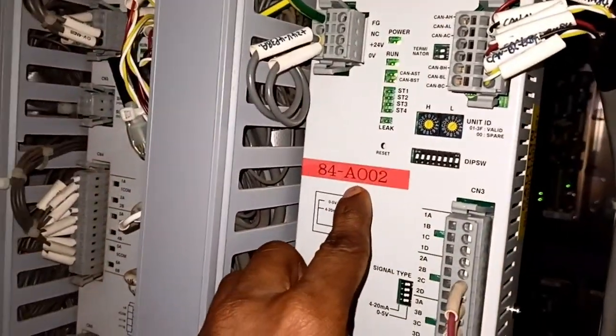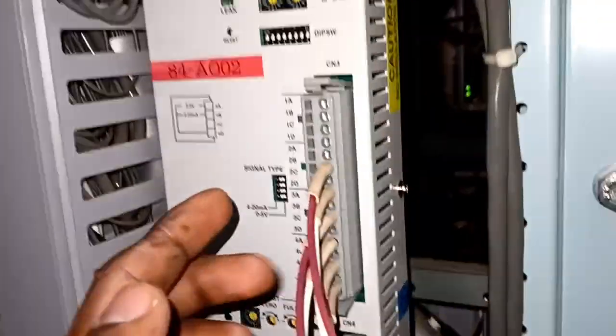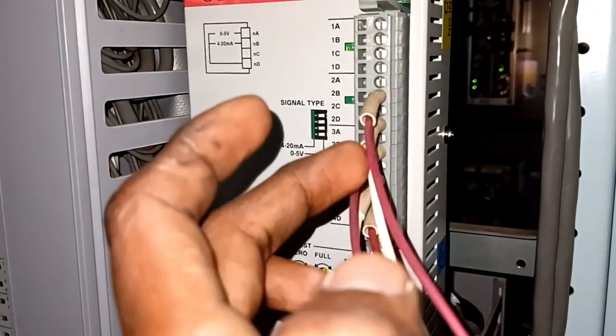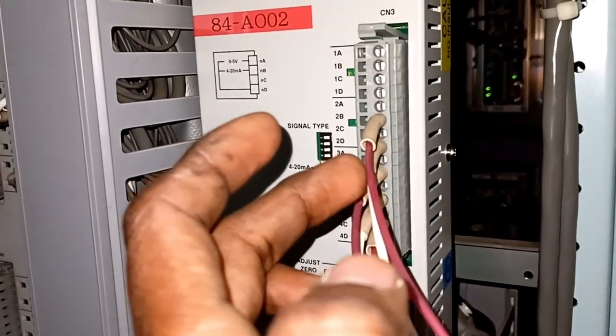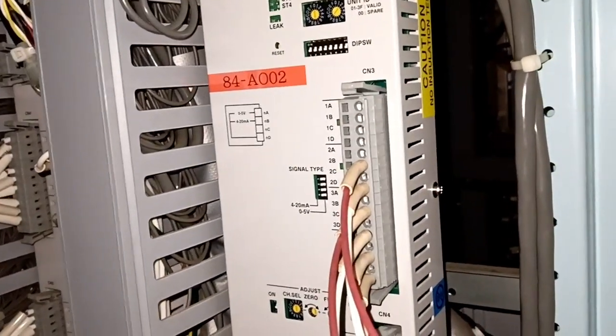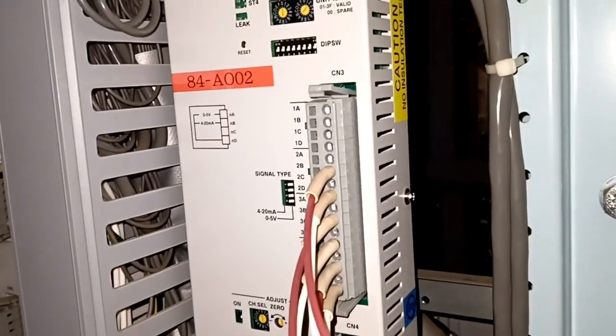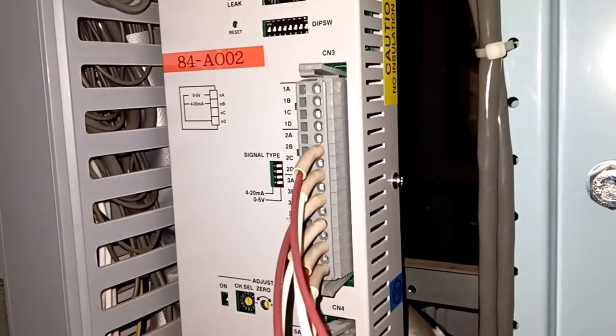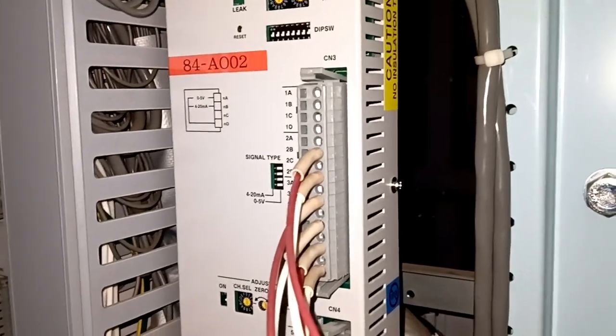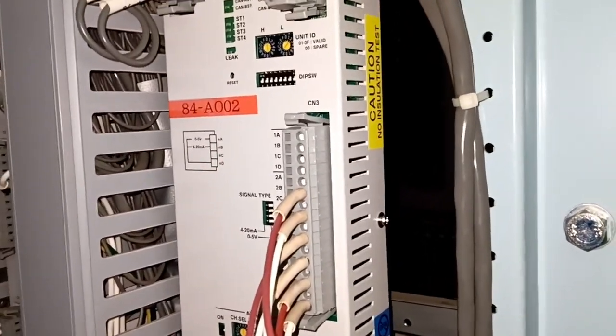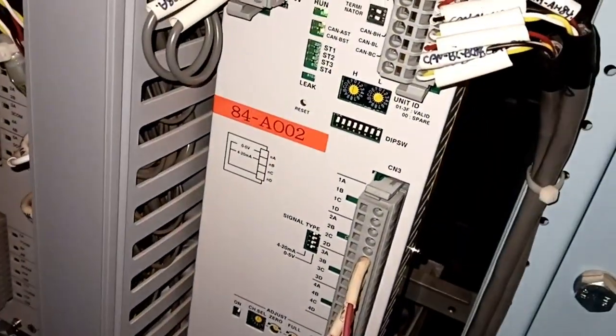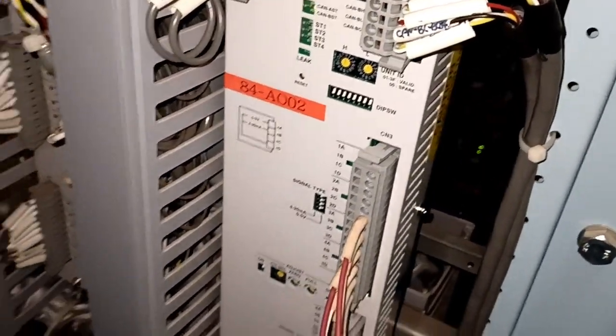From ECC the data is transmitted through 4 to 20 milliamps from the analog output card. AAO means analog output, and 02 is the number of the card. These two wires are for the number 4 DG. The number 4 DG load will be transmitted as 4 to 20 milliamps from ECC to the MCP panel of the EGCS. So I checked the amps here. Here we are getting the correct value of the amps according to the kilowatts.